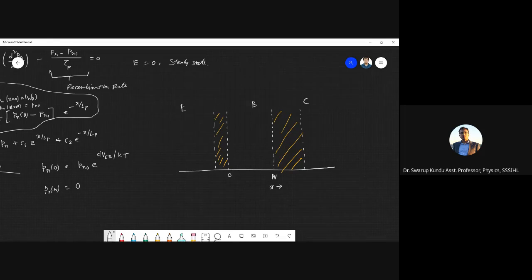And we define another two. So this is Xe and this is Xc. This is basically the boundary of the depletion region on the emitter side, and Xc defines the boundary of the depletion region on the collector side. And 0 to W is the neutral base region width.